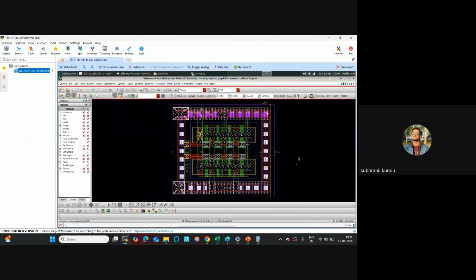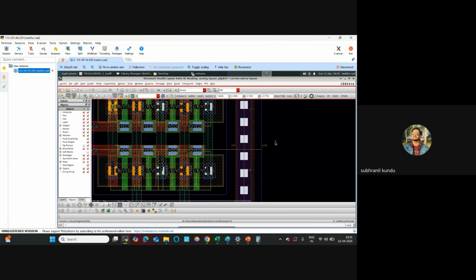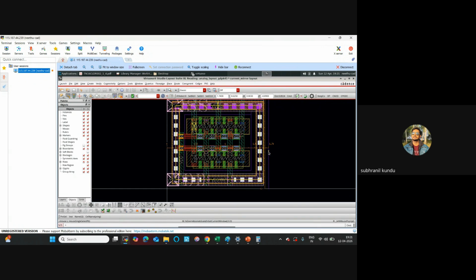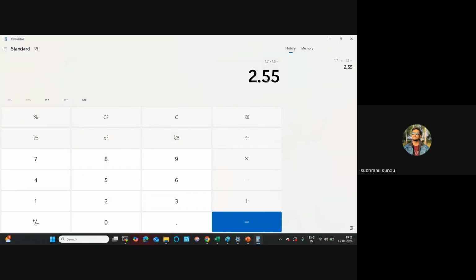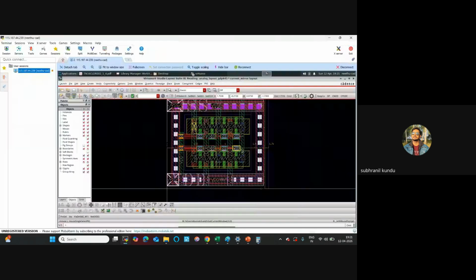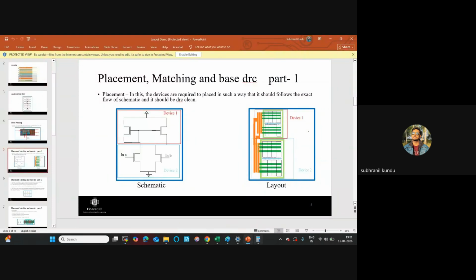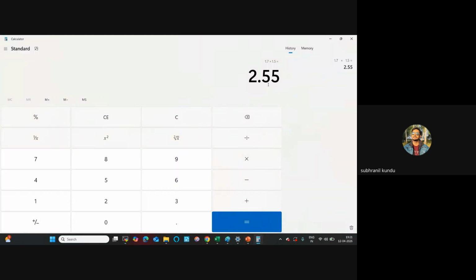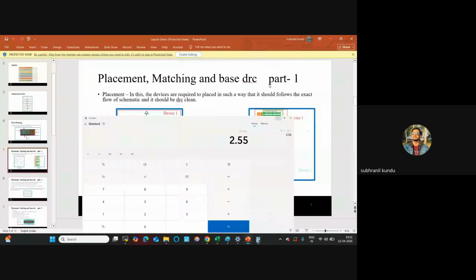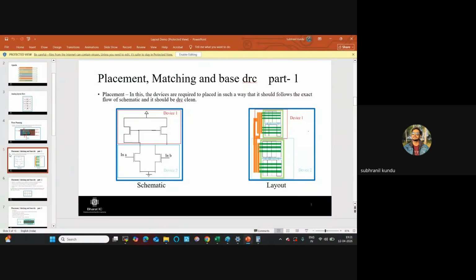Here you always remember, in this screen everything is in micron, that is micrometer basically. So I will tell my lead that 2.5 micron area is this, but he can tell me this is too much area. You need to make the layout into 2 micron. Suppose I am taking 2.5 micron, my lead will tell no, it is more area, you need to go for the 2 micron. So I need to rethink how I can reduce the area. This is what floor planning is.